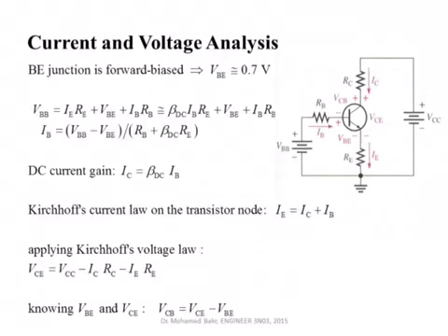Okay, when we get to analyze circuits containing transistors, there are certain rules we have to observe. As we have seen for the case of FETs, we say that there is no current flowing into the gate. The voltage VGS will have to be greater than a certain threshold in order for the transistor to be on. The same thing will happen here. For this transistor here, we are trying to forward bias the base relative to the emitter. You can see the polarity of this battery here. We are trying to forward bias the collector relative to the base as well. We're applying a very high voltage between the collector and the emitter.